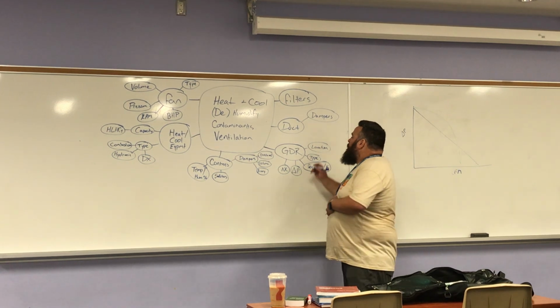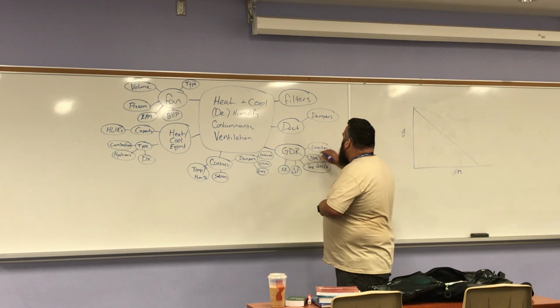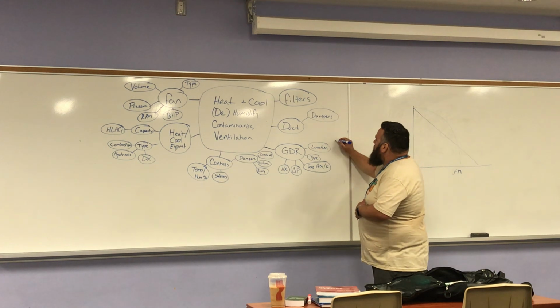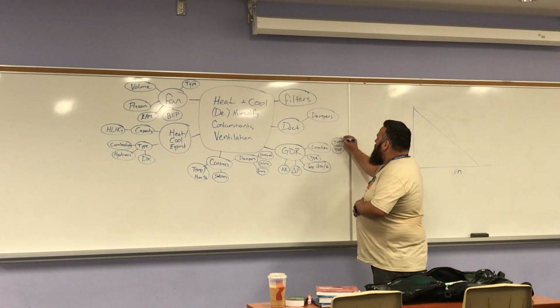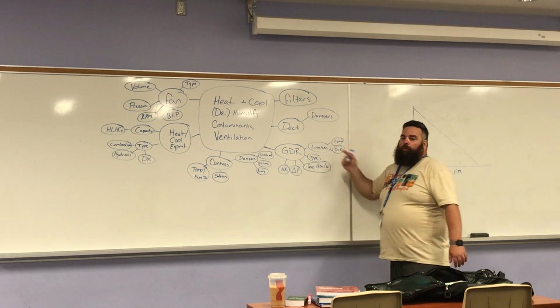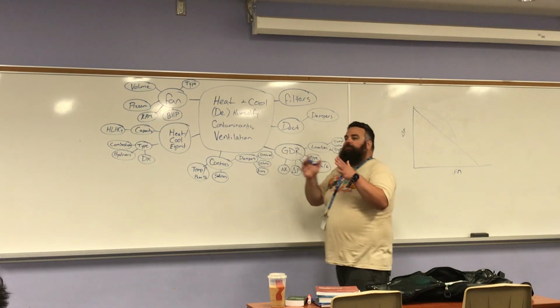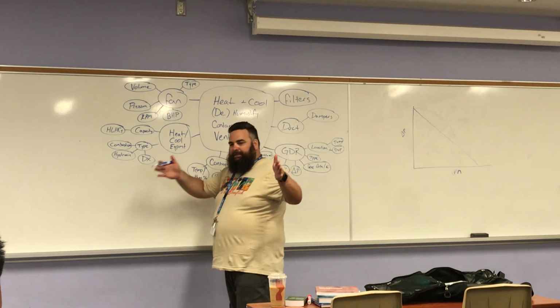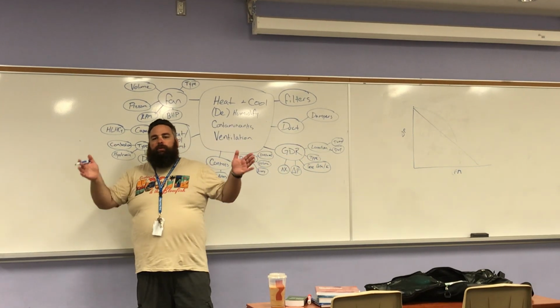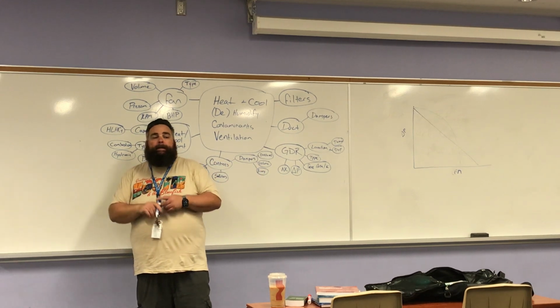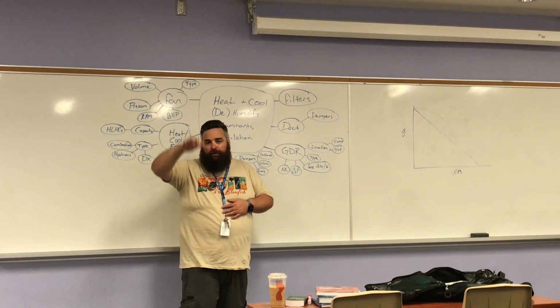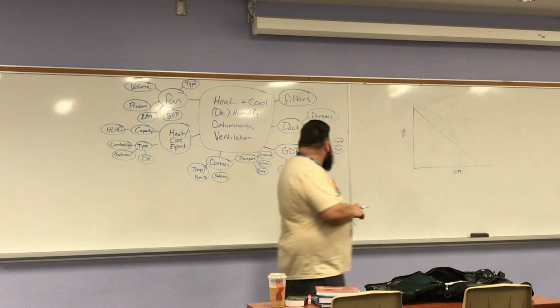We're also concerned with, off of location, I'm going to put throw and drop. Because that'll inform where we put it on the location. Our throw is the horizontal distance at which that air is thrown and at what velocity. And our drop is that kind of vertical drop.